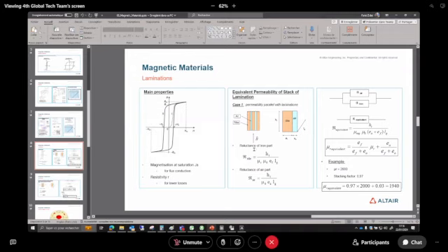So to cut the path of the eddy current inside the lamination. So then we will have an equivalent volume of iron and an equivalent volume of insulation or air. And here, once again, B is parallel to the lamination. It's really important to know that.